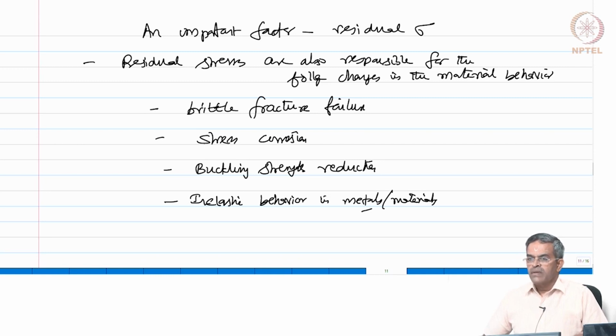But you know friends, residual stress development cannot be avoided. Okay. It is an inherent part of the manufacturing and fabrication process, because when you start building the connections, there is always a high probability that you will land up in development of residual stresses. So, this will now start prompting a low yield stress which will govern the design. So, elastic design of structures controls the design till this point, therefore, it is not considered to be a good method of design. Therefore, friends, designers shifted the design procedure from elastic to ultimate load design.